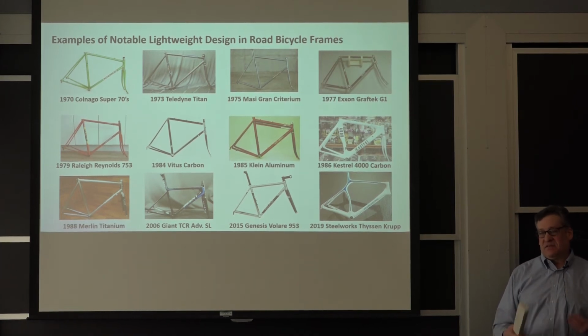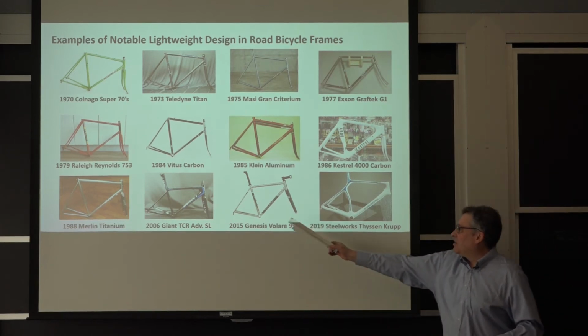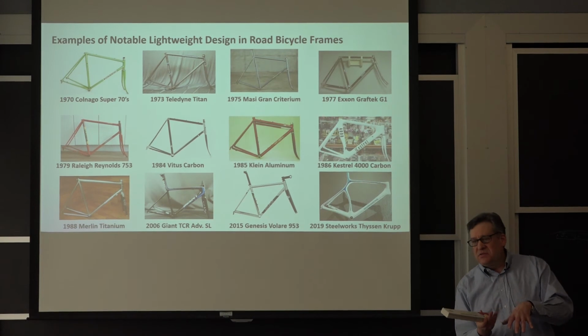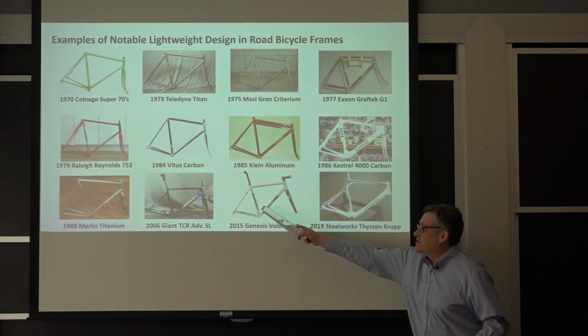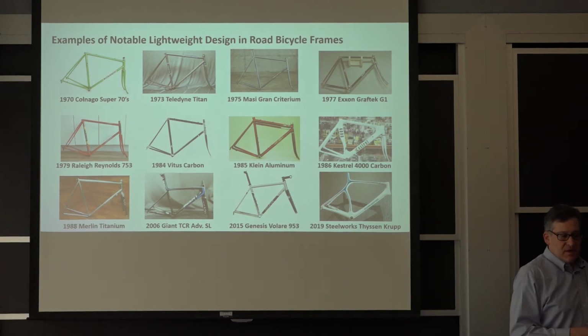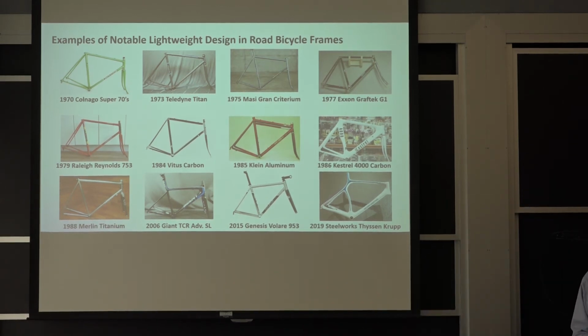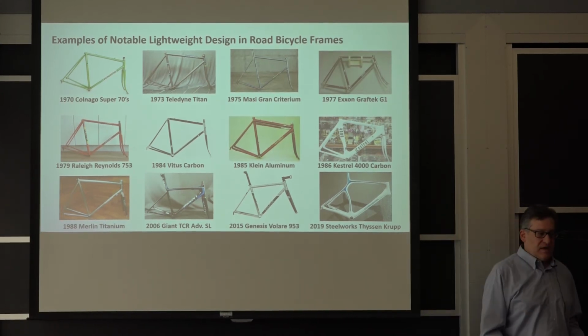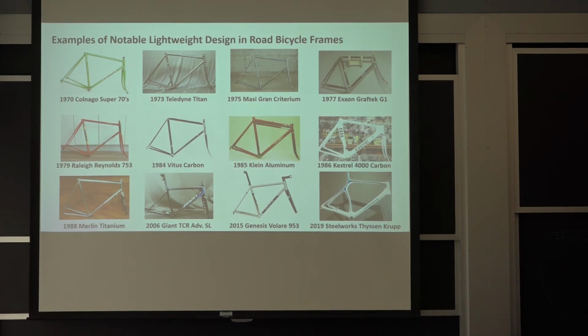They don't have that stiffness efficiency because the tubes are very close to just being round. There's some degree of flaring the tubes. You make them a little bit bigger around the joints and so forth. They've done a great job. I'm not trying to criticize it, but the issue is that Reynolds, I think, as a steel company, has very much ignored the geometry side of this and really only focused on the material side. But anyway, a lot of people say these are great frames: strong, fatigue resistant, energy absorption, some people claim. I don't know if that's true or not.